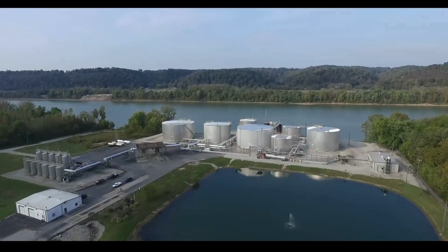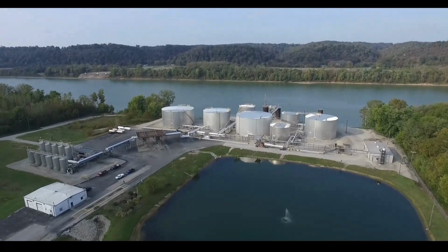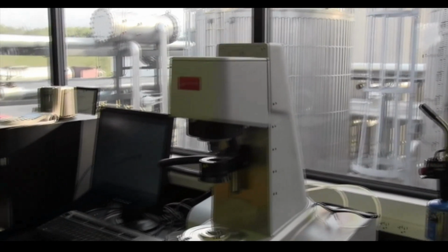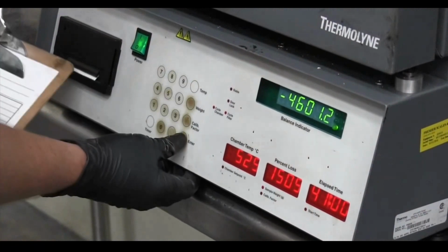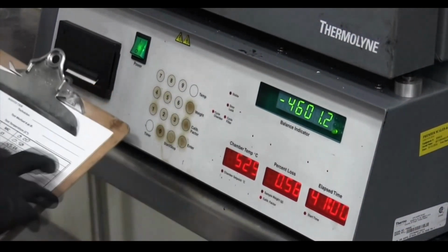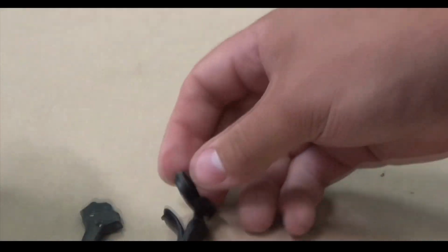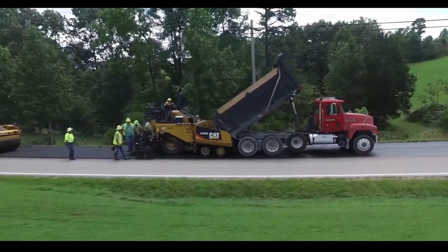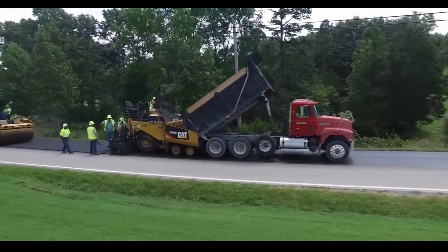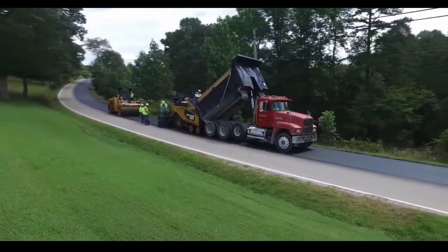The liquid asphalt is stored in large tanks at a terminal facility and is tested on a certain frequency utilizing several sophisticated machines. Technicians can determine how the binder will behave at extreme hot or cold temperatures, its properties after significant aging, stiffness, viscosity, and its ability to recover from loading. The aggregates used in an asphalt mixture are vital to the rut resistance and performance of the surface and must also be tested.